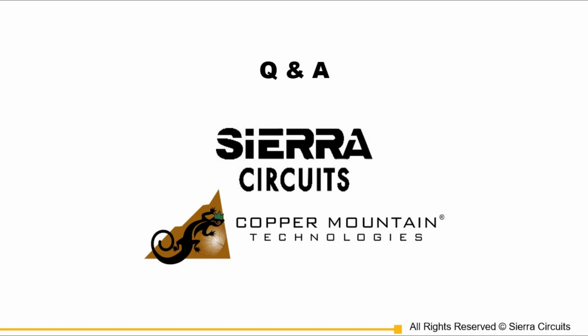The only trade-off here is, are you increasing the cost of the PC board? Because if you're going all the way through the PC board, I've talked to Amit about this, then you have to use a mechanical drill. If you're going through just one layer, it can be laser drilled, and then that really doesn't cost much. There's no cost difference if you have a bunch of vias. So it's something to think about.